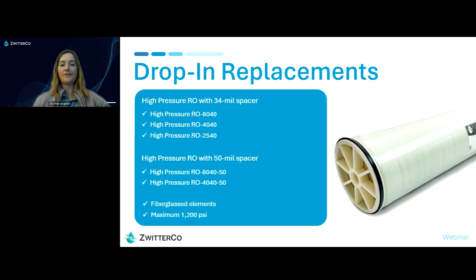All of these elements are available in industry standard sizes that fit into RO pressure vessels, meaning these elements serve as a drop-in replacement for existing RO systems. Again, no system modifications or additional capital investments are needed to implement this technology.